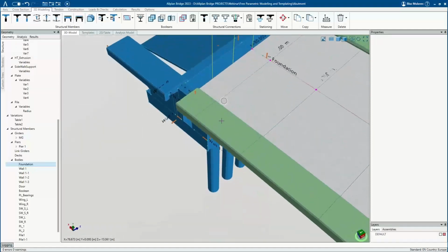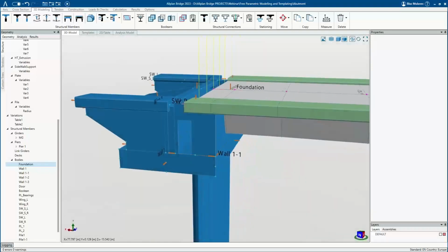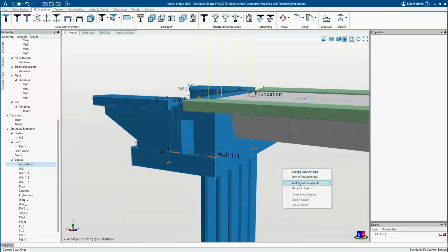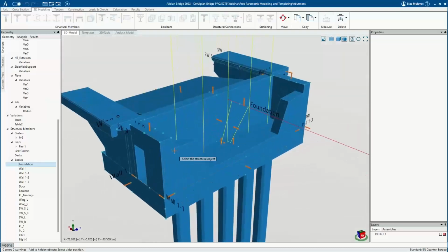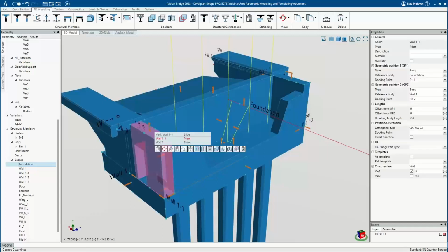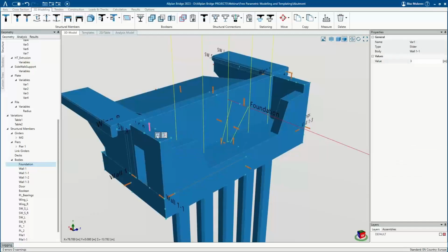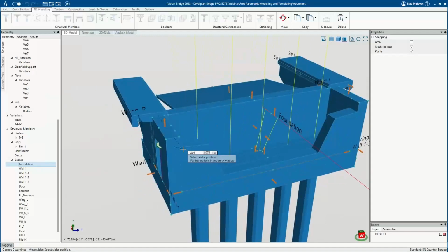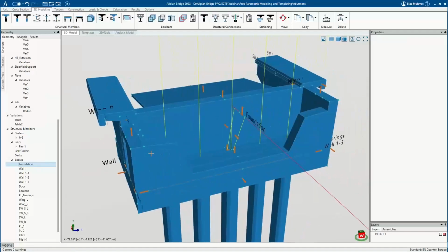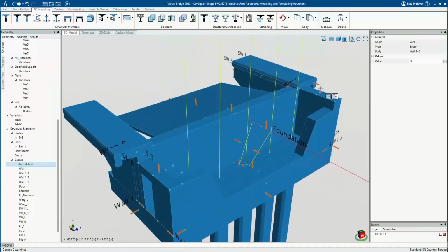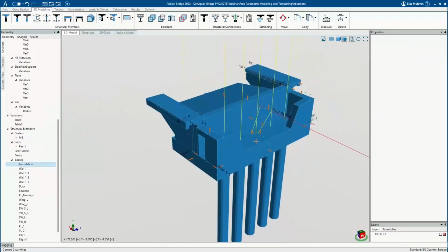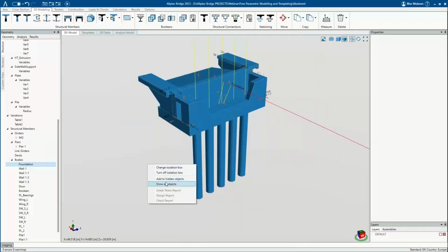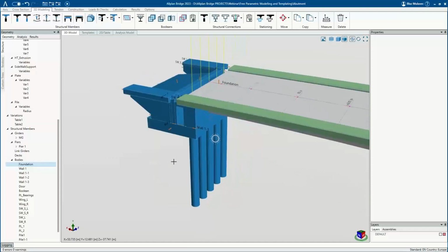Further, I can also see that this wall is a little bit too high. Therefore, I will again hide my bridge and correct the height. And I would like to align it with the top point of this wall where we have done the subtraction. Again, on the other side, I visualize our bridge again.